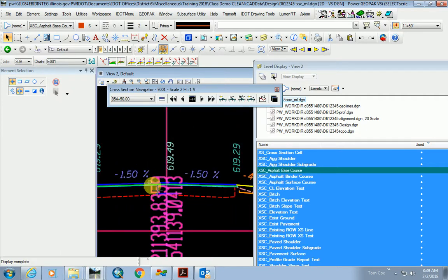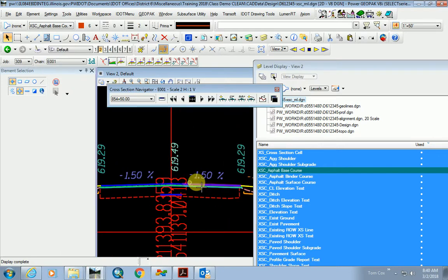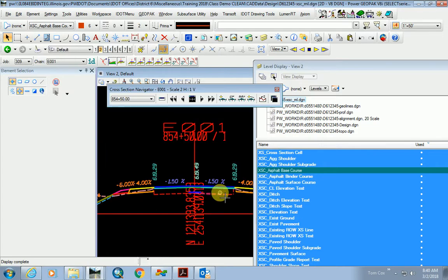You can see that we're doing cross slope correction also because it's not following the existing cross slope. Some of those other typical sections would say match existing cross slope, and maybe there's other districts that work this way, but I don't know. I've worked in 2 districts now, and I can tell you, every single project I've ever worked on, we've milled. I can't think of any project that we didn't mill. So we corrected the cross slope.